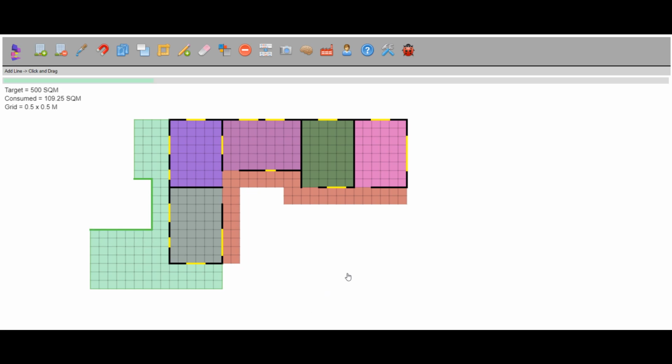So you can draw layout also, you can draw elevation also, anything you can do, but the intention of this tool is to create the floor plans. Okay, I think this is pretty much here, till now we'll go to the next phase. Now I'm deleting everything. This is one way to develop this thing. So before deleting, I will explain another feature, which is called annotate: confirm space types and names, get area on screen. This is required before automation.